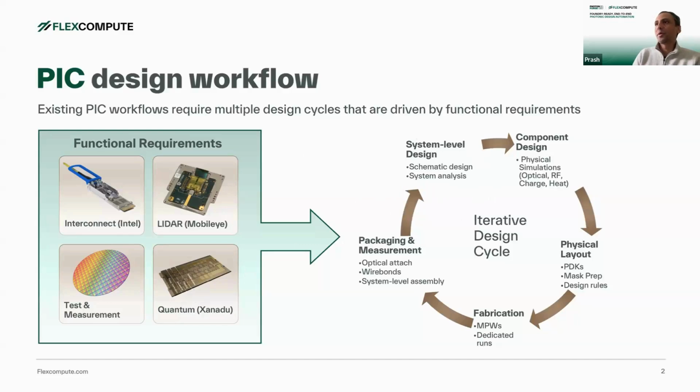So there's a little bit of figuring out, to achieve a given functionality, what components I need, and then where I can fabricate that. And then you go towards, okay, here are these components that the foundry already provides, but then there are some components that I need to redesign. So you quickly enter this kind of design cycle. And you might go back and forth. I haven't added a bunch of loops here, so this is a very iterative process.